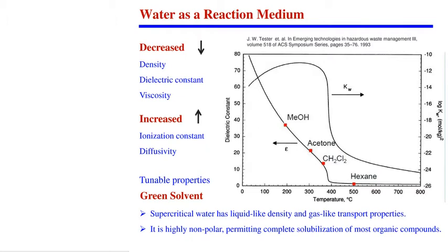Another application I will talk about is how to make biocrude, petroleum crude-like material. Yes, we can use subcritical water to liquefy biomass. Take biomass, use subcritical water condition, roughly 300 degrees Celsius or so, and liquefy biomass. And then this crude is basically a bio oil or biocrude, which can be upgraded to make hydrogen or catalytically upgraded to make liquid hydrocarbon fuel. So hydrothermal liquefaction, this kind of term you will hear when you use subcritical water.